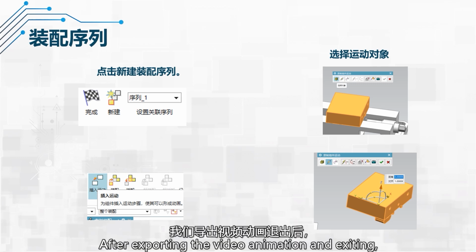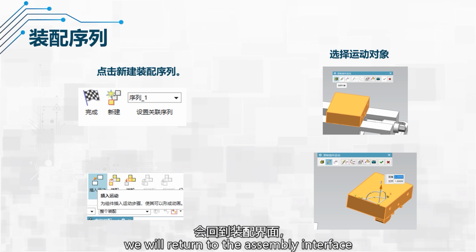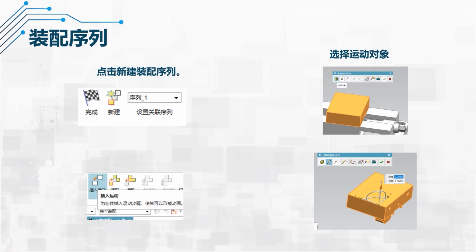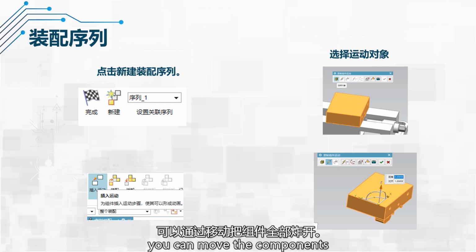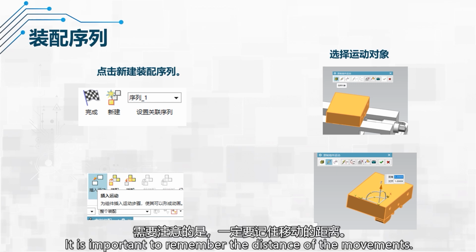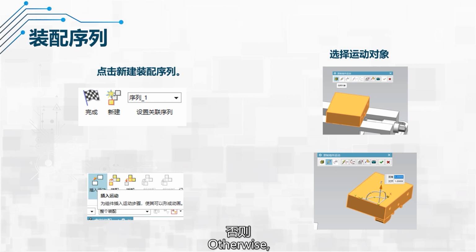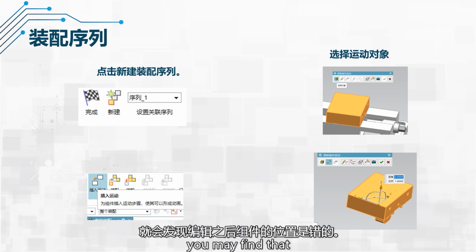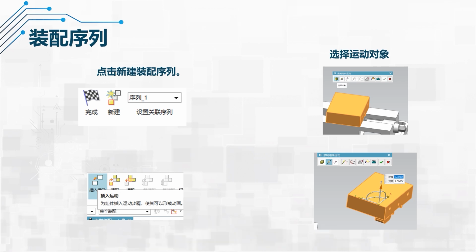After exporting the video animation and exiting, we will return to the assembly interface without changing the position of the components. In this sequence, you can move the components to explode the entire assembly. It is important to remember the distance of the movements. Otherwise, when performing sequence motions later, you may find that the component positions are incorrect after editing.